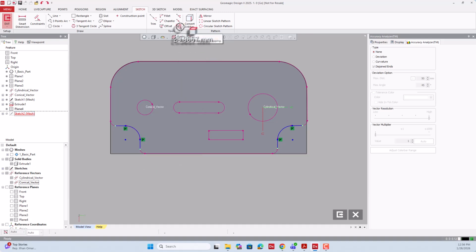Over here, we have a tool called Resize. It's very small, and it's beside the Convert Entities tool. If you click on that small tool, it'll open a widget without any options called Resize. The purpose of the Resize tool is to just extend a line or an arc without changing the direction. So here, no matter how you pull, it always maintains the direction of the line.